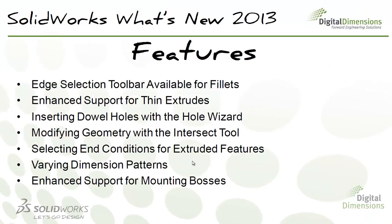So the next thing I'm going to show you is selecting end conditions for extruded features, which means you don't have to always go over to the property manager to set your end condition. You can change the direction or change your end condition, and this works on solid and surface extrudes and revolves and even sheet metal base features.